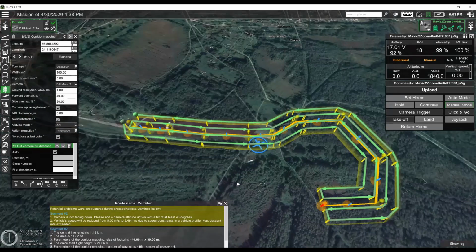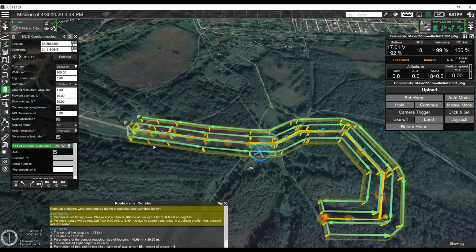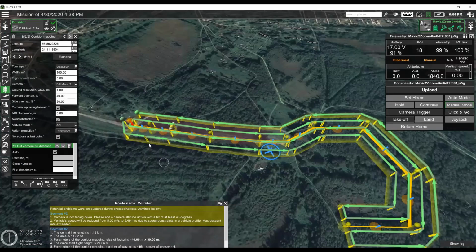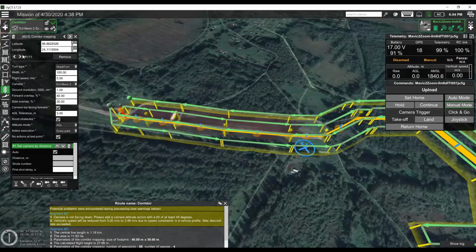Once I have created the segment, this is one single segment of the corridor road. You can see here on the road tool, here's corridor mapping 2 of 2. First is a simple waypoint, then it's corridor mapping. Then there are 11 points where I was clicking on the map, and each of them has coordinates, which you can adjust if necessary.